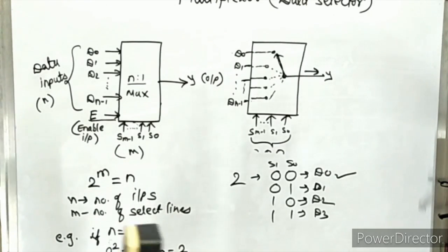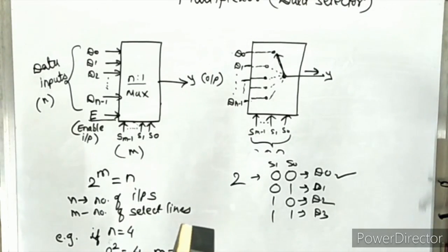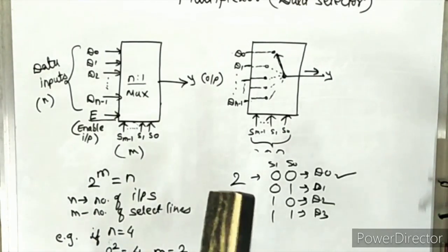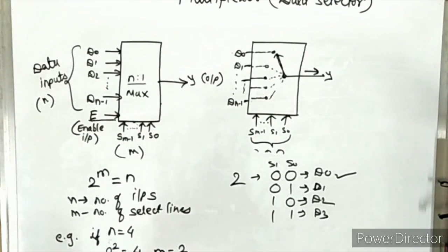Why are these multiplexers needed? In most electronic systems, the digital data is available on more than one line, so it is necessary to route this data over a single line. Under such circumstances, we require a circuit which selects one of the many inputs at a time. This circuit is nothing else but a multiplexer, which has many inputs, one output, and some select inputs.